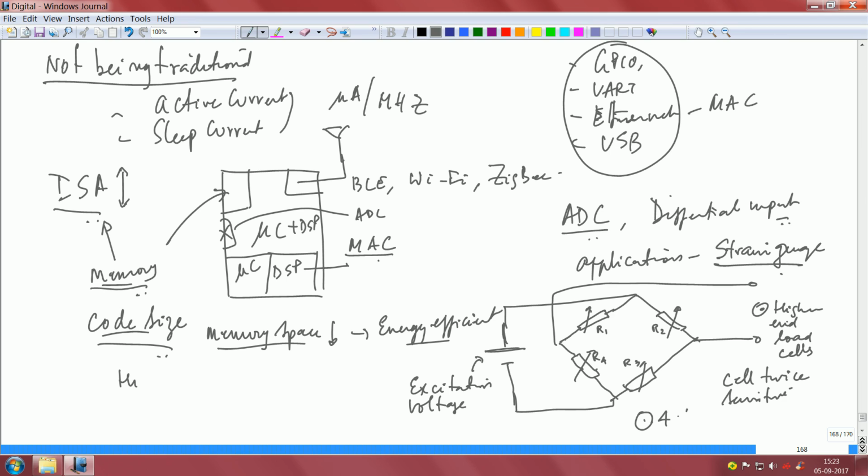So, you are doubly in a problem. Therefore, you must somehow ensure that this excitation voltage is kept constant during the time when you are making a measurement, which means it leads you to the requirement of an LDO.